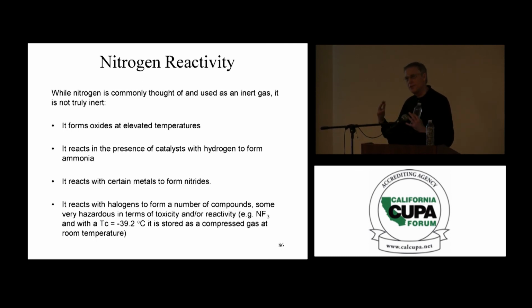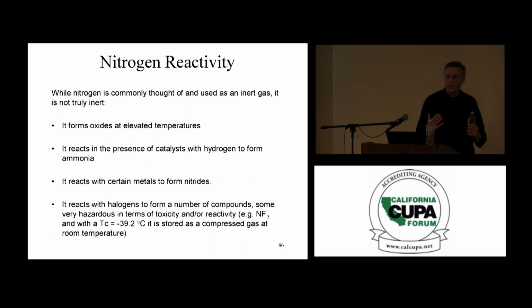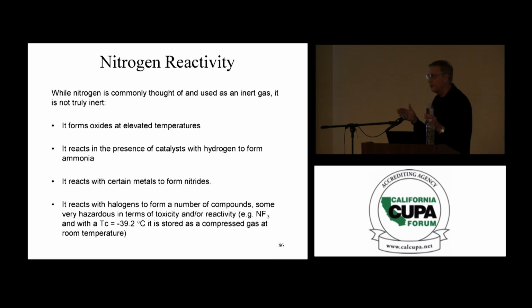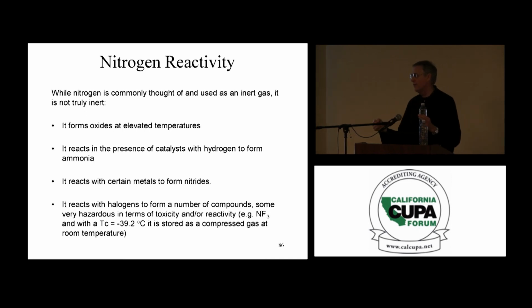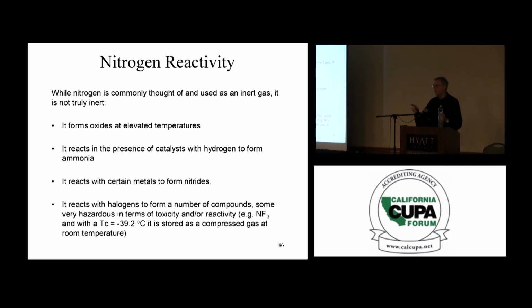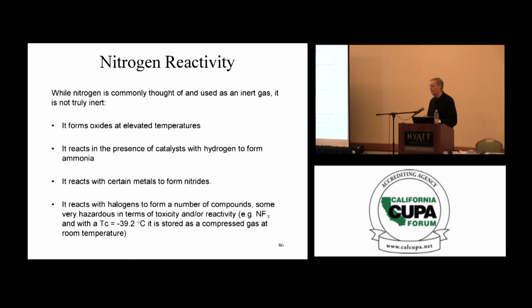I have gone to facilities where I've worked and found that they have moved the dewars into small utility closets and storage rooms, and the doors closed. And so if you walk in there after it has been venting, you can get into an oxygen deficient atmosphere. So what I did was I insisted, take the door off. Either put an oxygen sensor in there with an alarm or take the door off, preferably the oxygen sensor, and warn people of that hazard.